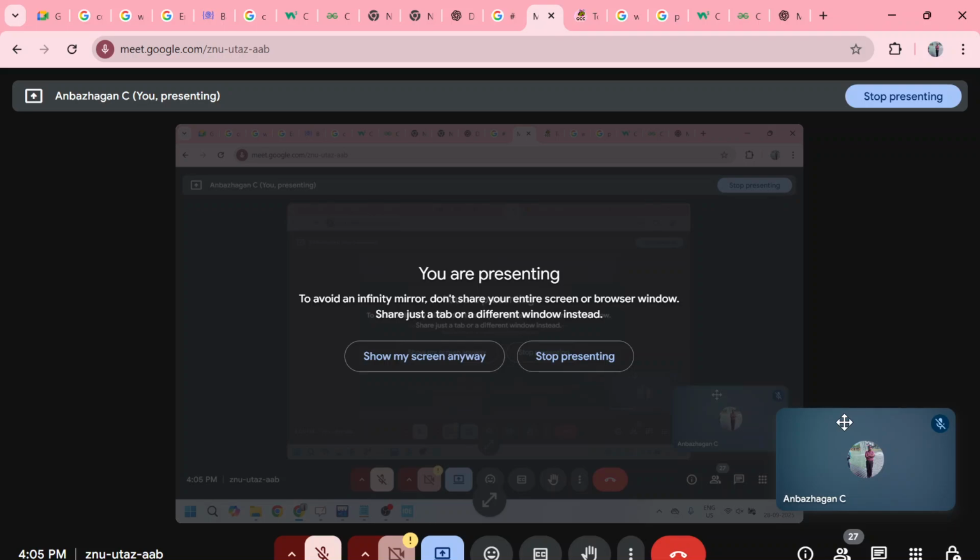If it's a local variable, it will be stored on the stack side, so you can get the memory and change that one. But if it's a global variable that I declared const, we have one segment. I will tell you about those segments when we are learning bare metal, or maybe next week. One segment is the .ro segment, the read-only segment.